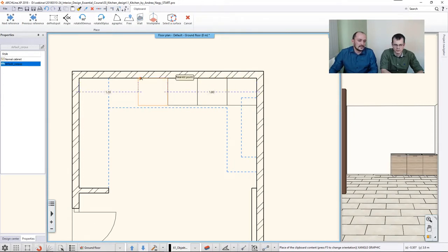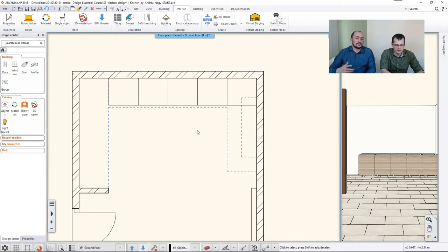So let's say I would like to place 5 units here, and then I'm starting to customize them. So one workflow is that you build a unit, place it down, build another unit, place it down, build a third unit, and so on. You repeat these steps, or you put them all down, and then later you can modify them one by one. This is what I'm doing now. It's kind of a conceptual design, and then I'm customizing the units because I would like to see the same front, the same layout, just the inside will be different.